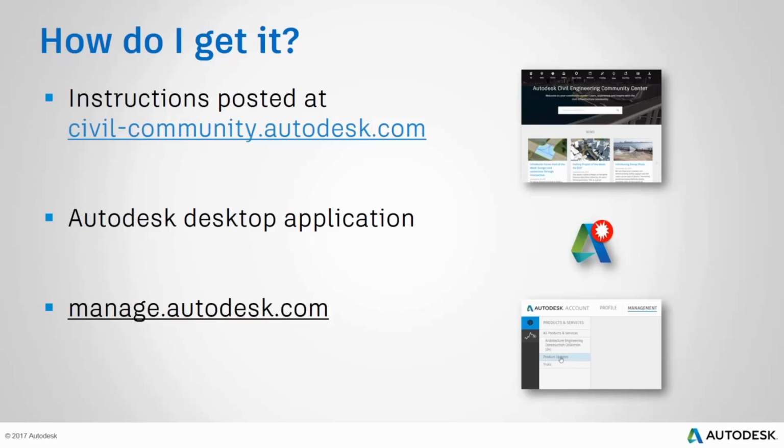Okay. Another question, was anything done to expand, or are there any plans to expand the U.S. vehicle library? Right, so I know that there is a wish list item for the US vehicle library. In the later versions of AASHTO, there are 2 sets, I believe, of each type of vehicle, and we have defined the one has a smaller turning circle than the other set for each vehicle. The vehicles in our library have the larger of the 2 turning circles. I don't know of any new libraries that are available. If anyone on the call knows of any standards that we are missing and don't support, please feel free to send them to me, or to register a wishlist item on the Vehicle Tracking Forum off the Civil 3D Forum. We're more than happy to look into adding any libraries that you can supply.